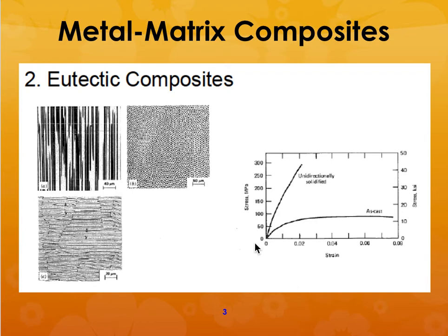So this is one of the processes by which turbine blades are formed. They are taken from the melt and solidified in a certain form so that all the grains will form in one single direction only. So when you do the unidirectional solidification, then it is stronger than if you had just made a combination or just let it cool in a non-uniform manner. Okay?